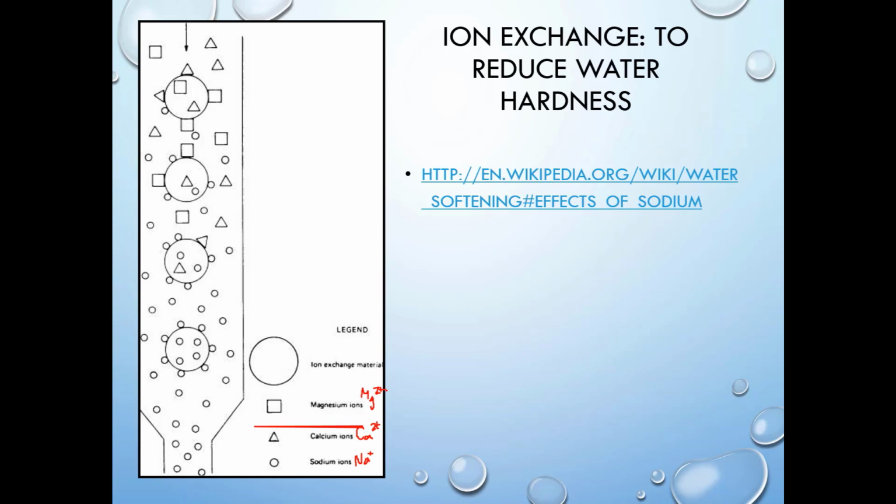What you'll do with an ion exchange column is that it will be delivered to you more like in this phase over here. They're manufactured with a bunch of sodium ions attached to the negative charge sites on the ion exchange material, okay? But your water might have a lot of magnesium and calcium due to being hard water.